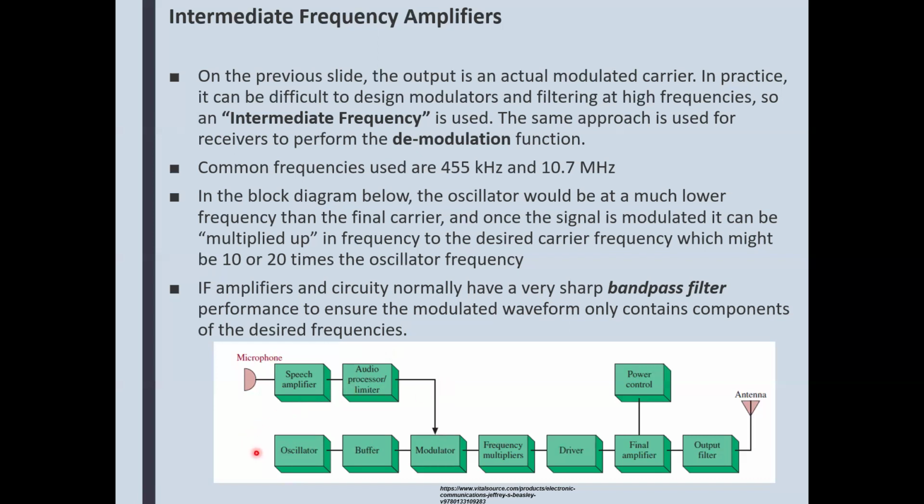And over here, at the same time, we have an oscillator. And what does the oscillator produce? That oscillator produces a high-frequency carrier, onto which we're going to superimpose or mix the intelligence signal, and they all come to that modulator, which we just made yesterday in our lab.